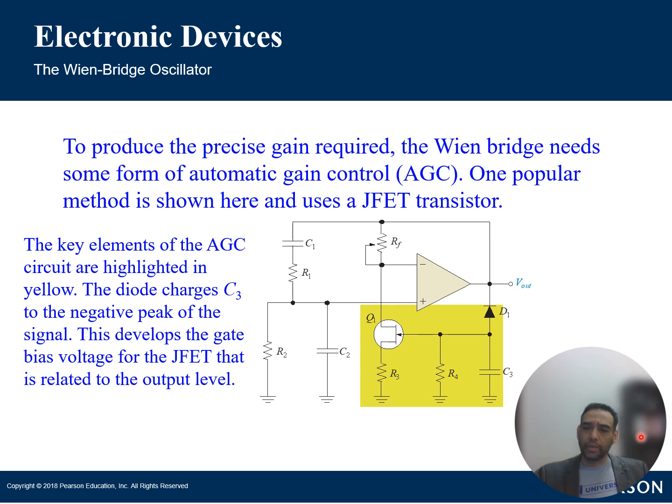It typically is made up of 2 voltage dividers. They're connected in parallel. One divider is basically a resistor and a capacitor in series, while the other divider consists only of a resistor. There's a junction between the resistor and the capacitor in the first divider, and the junction between the two resistors in the second divider. Those are connected to the input and output terminals of the amplifier, respectively.